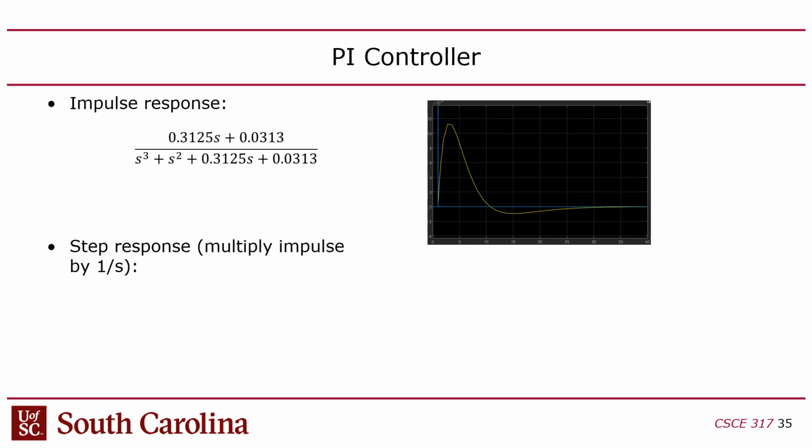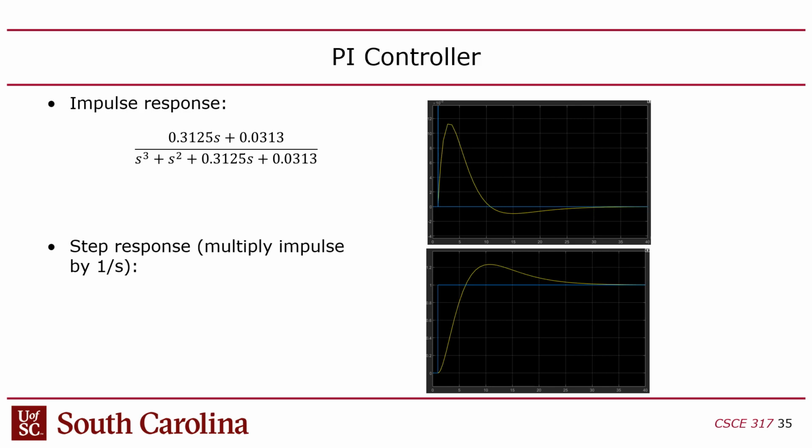I want the step response, though. There's the step response. Yeah, sorry, that's the impulse. There's step. So here's the step response. Now remember what this represents. The step response is assuming that the input is the reference, right? So the reference is where I want the thing to be. This is like saying, robot, move the coin 0 meters, but then I'm suddenly going to change my mind and say, move it 1 meter, right? That's what the step response is.